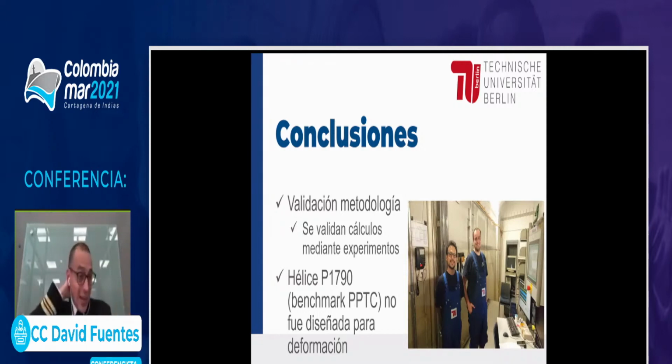One is to scale the model by lambda. This is going to take us to a more flexible material, with the problem that maybe the material that we find won't be reliable enough when we print it. The other is to keep the same material and find equivalent RPMs that will allow us to have the deformation normalized and equivalent.